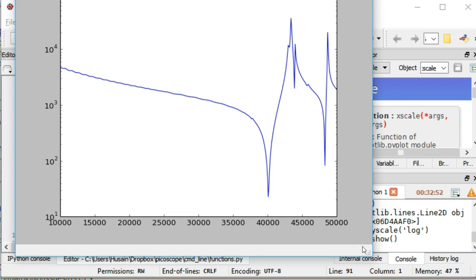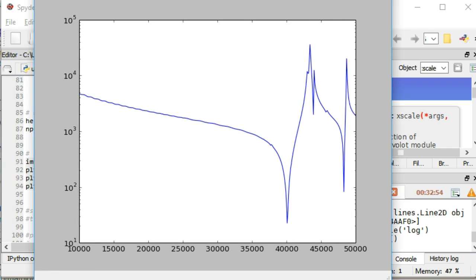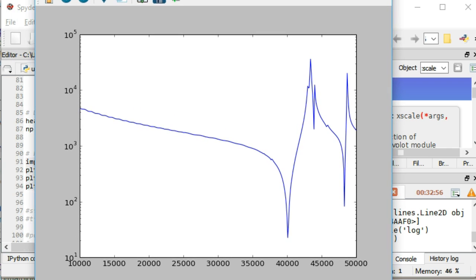As you see, we have impedance on this scale, and we have the frequency in hertz on here. You see the typical behavior of a capacitor: when you're increasing the frequency, the impedance is getting lower, until you hit an anomalous region, which is known as a resonance region.